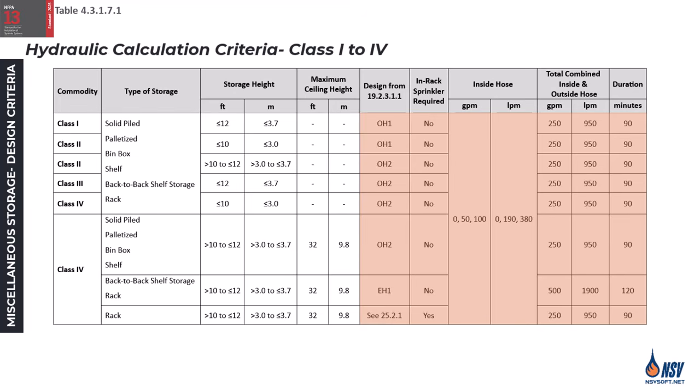The right part of the table outlines exactly what NFPA 13 requires us to use for our hydraulic calculations based on those specific project parameters. Regarding this table, we should note a few key points. First, these requirements apply to spray sprinklers. We should also keep in mind that NFPA 13 generally refers to these spray sprinklers as CMDA, or Control Mode Density Area Sprinklers, within the storage chapters.